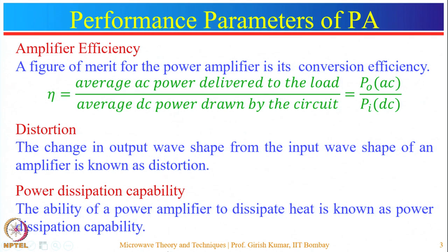In the case of a power amplifier, the resistance of the collector is chosen relatively low because in these cases the output current or the voltage swing should be very large, and this can happen if the collector resistance of these amplifiers is chosen as small.